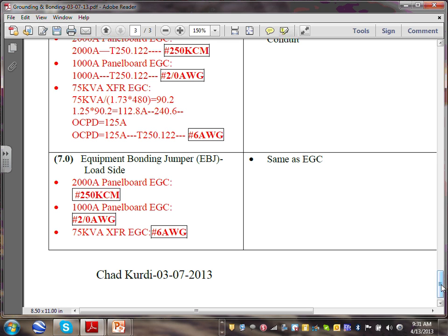If you daisy chain them, guys, conduit 1 to 2 to 3 to 4 to 5 and tie it to the ground bar, that will be 250. Or if you go from one conduit to the ground bar, this also will be 250. Unlike the supply side bonding jumper, where there are 2 sizes, here it's the same size, because we size based on the overcurrent protection device, not the conductors inside the pipe.